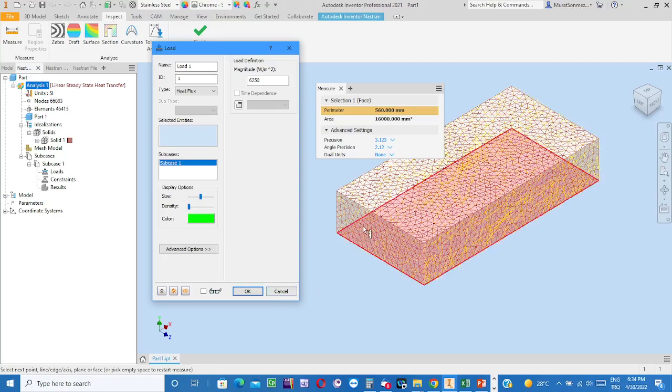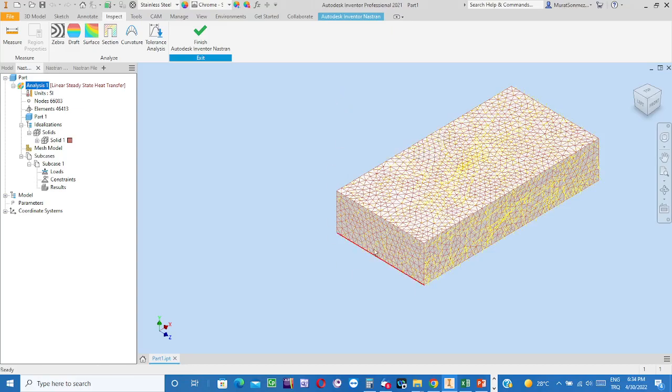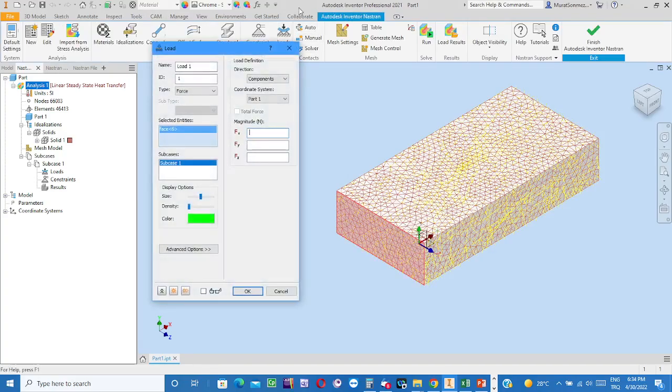I forgot to make a click on the surface, so we'll say for a while cancel. Okay, and then indicate the surface, and then clicked on boundary condition inputting button, and here select from the list heat flux option.